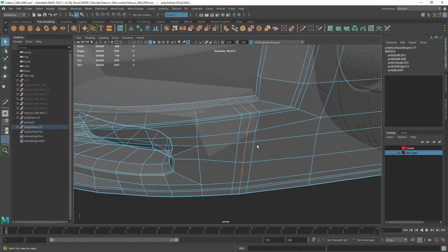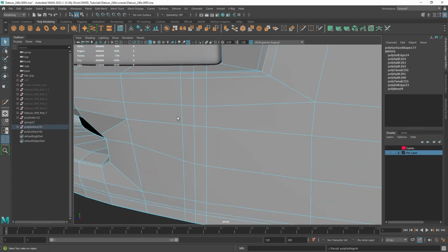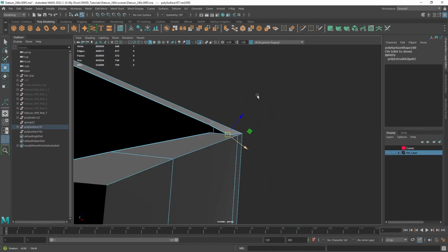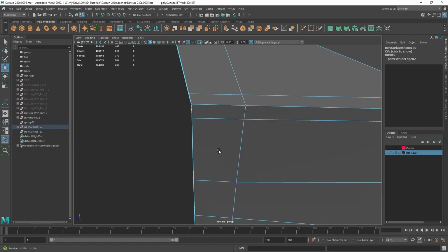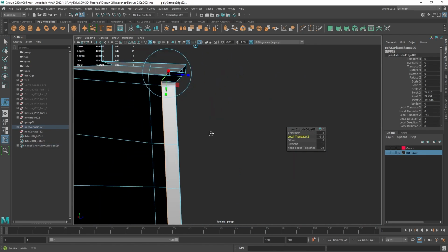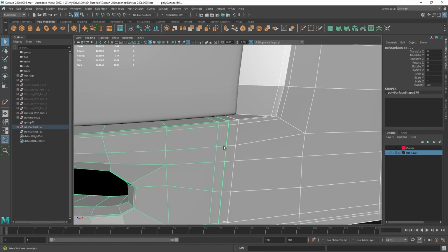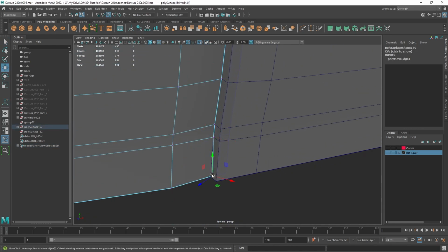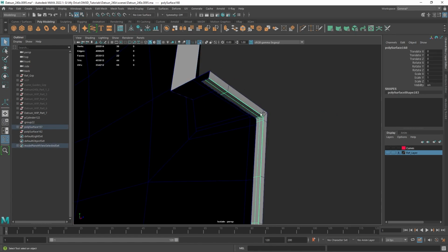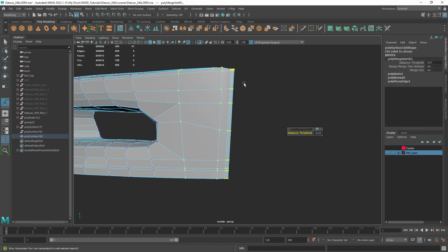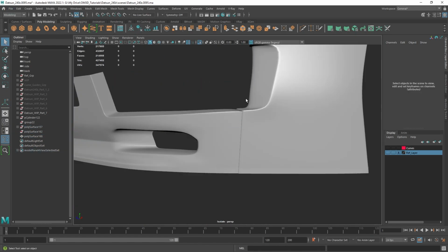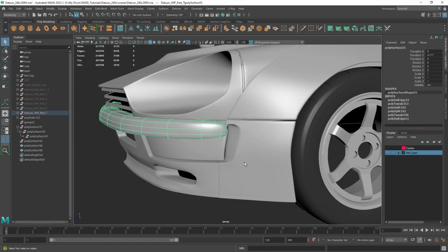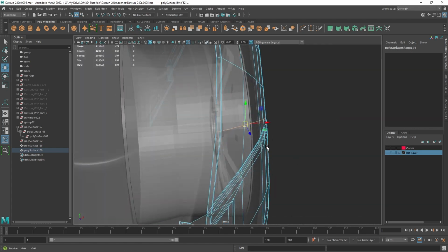So I wanted to clean up some geometry at the top that loops around at the bottom. Clean up and straighten those edges, and then I extract geometry, extrude the edge of the top panel, then I extrude again to get the thickness there. Then I select the vertices and start snapping them on the other panel. Then I duplicate faces, flip the normal, and reattach it to the other object. So I can cover that maybe in more detail later, but that is the overall workflow.